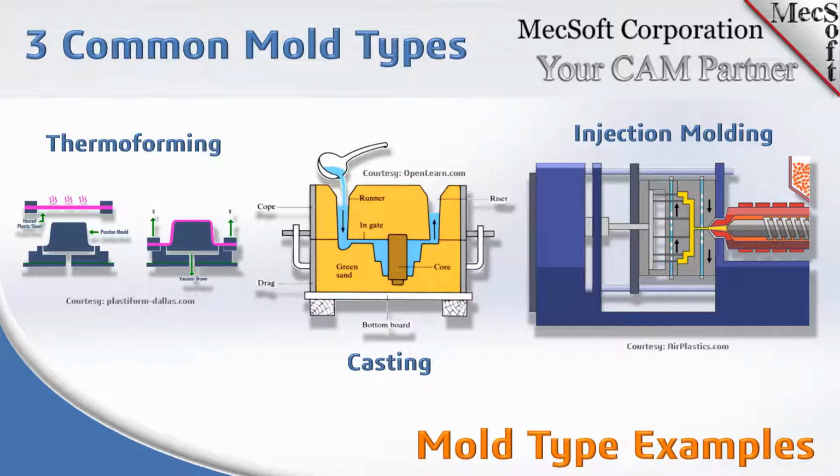Okay, the next tip or technique is for the cutting tool. Basically, what we're trying to get across here is that you want the stoutest cutting tool that you can use, the largest diameter, the largest shaft diameter, and the shortest length of the tool, which will create a very strong tool.